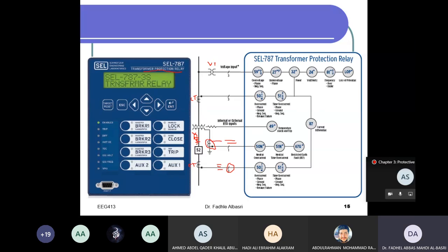So these two go to this input. While this is also 3 wires here. This is the VT, 3 wires. So this is 3 phase, maybe a star-star connected VT. So we have 3 outputs. Some functions like overvoltage, if I want to know whether the voltage here is high or not, is an element that detects that this voltage is high or normal.